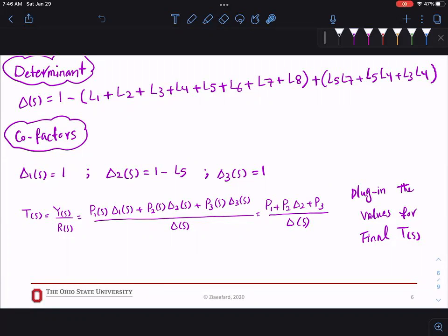Now, if you remember, I explained that to find the transfer function of a system, if you have the block diagram, I usually give you this choice. You can use block diagram reduction and find the transfer function for the whole system, or you could use the flowcharts and the flow graph. What you will be left with is an input-output system. So this system is your transfer function. Either way, you can find it, depending on how complex your system is.